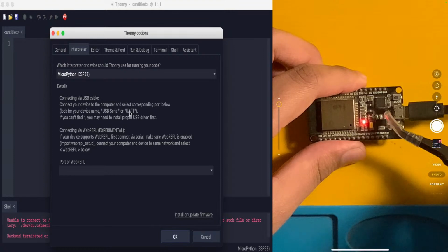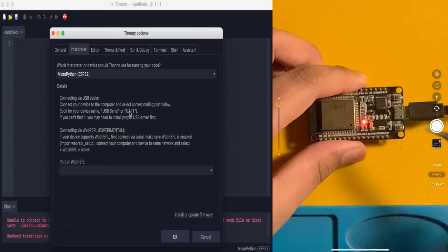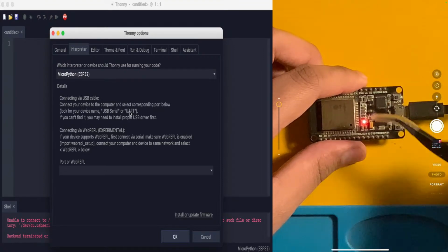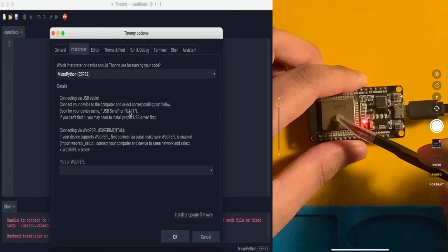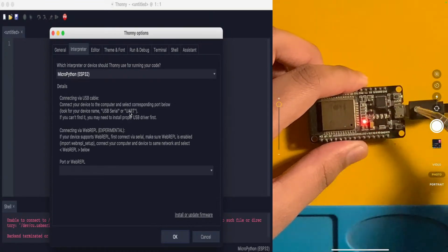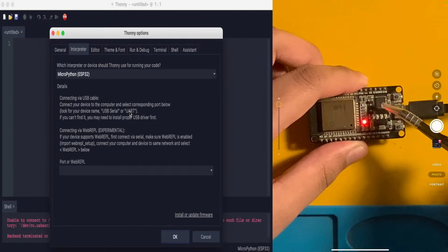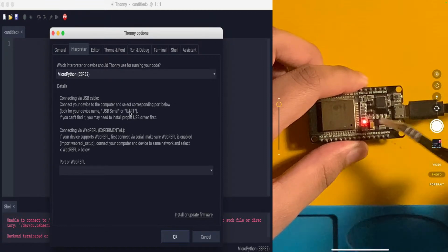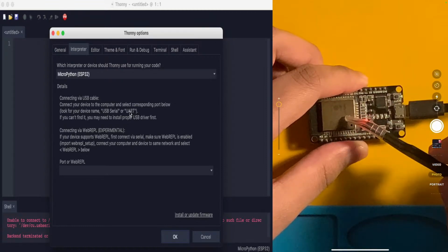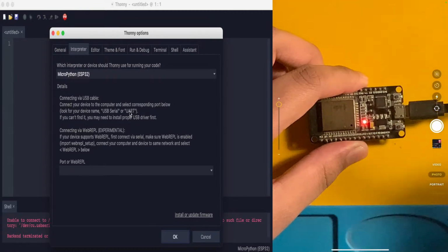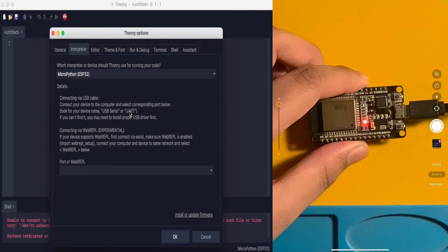USB is a communication protocol, and UART is also a communication protocol. The thing is that the ESP32 cannot directly interface with or understand the USB communication protocol. So we have this chip: it takes all the USB data, converts it to UART, and then feeds it to the ESP32. Hence, communication successful. You can program it, or maybe use a REPL. The ESP32 sends a print command, or sends the output to the REPL, and you can see it on the console on your PC. That is how the communication is going on.